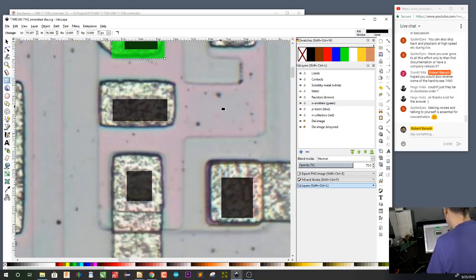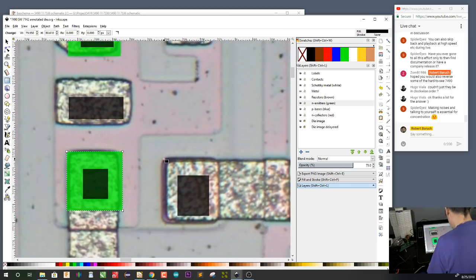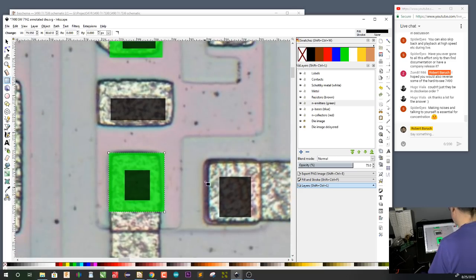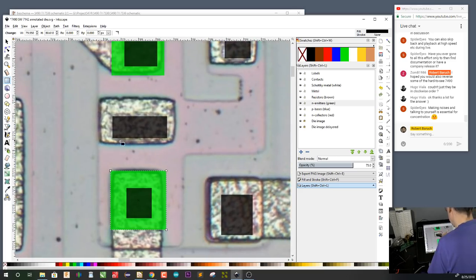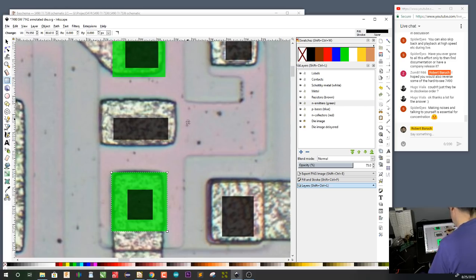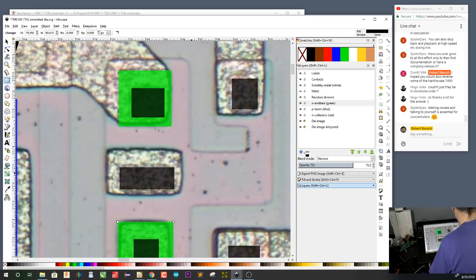There's nothing here. Here's a line, so we know we've got to have something here. Again, we can see a line around here, but it's not inside a base. So that is a low resistance connection to the collector. Around here, interestingly, we don't see any line crossing the metal. So whatever this connection would have been, it probably would have been a base connection, but it's not connected to anything. So let's draw the base.